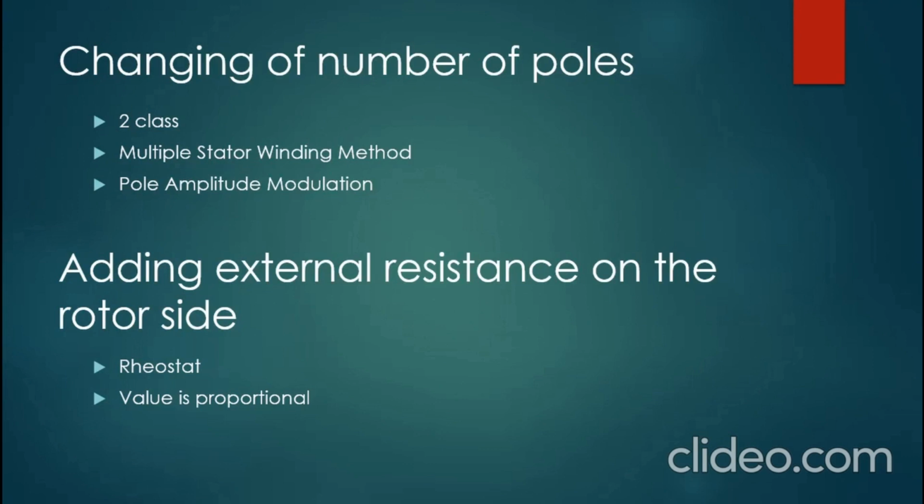These two windings are placed apart from each other and wound for separate poles. Speed control is possible because of the switching arrangement. Supply is only given to one winding only. Smooth speed control seems to be the problem of this method. Another disadvantage is this method is quite expensive, and moreover, it is less efficient. Finally, this method can only be utilized for squirrel cage motors only.